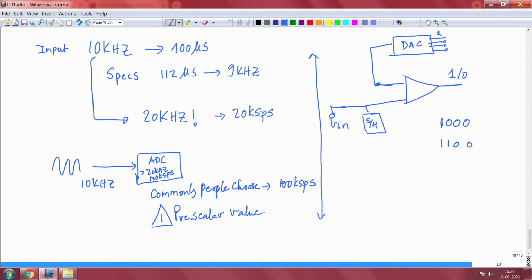Please note, okay, whether you are trying MSB 1, if this succeeded giving you a corresponding output, then you will try 1 1 0 0. Now if this failed, what you will do, this succeeded already. So what you will do, you will make 1, this failed, so I will make it 0, then I will make this bit 1, then this I will try. If I try like this and if this succeeded, fantastic. So I will retain this bit and this bit, now I will try this bit. Which one I will try?